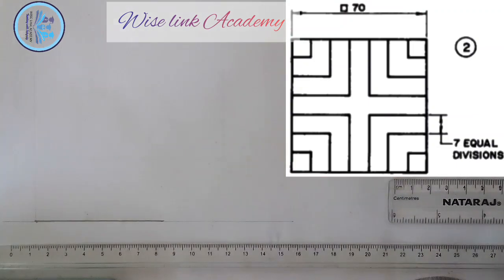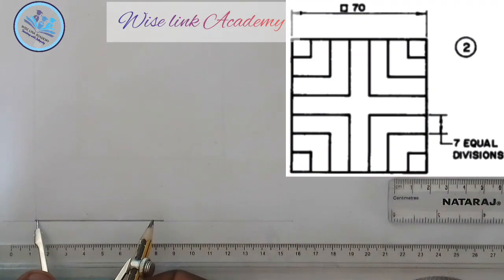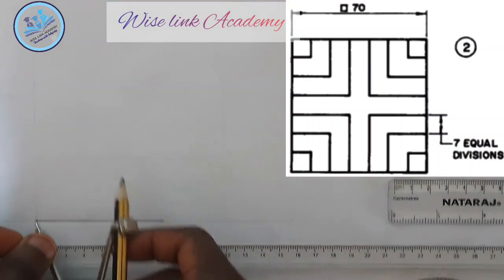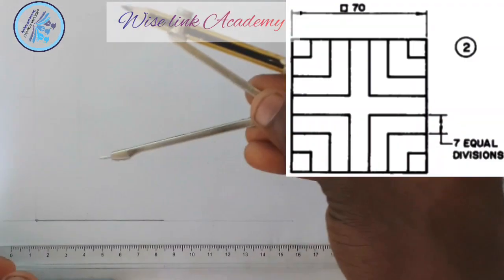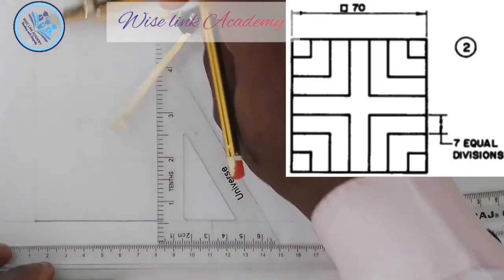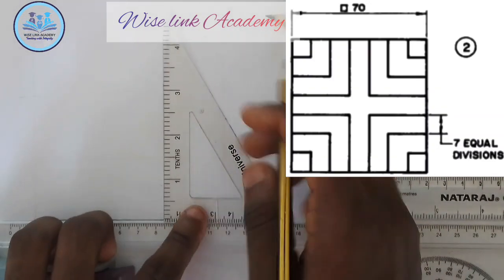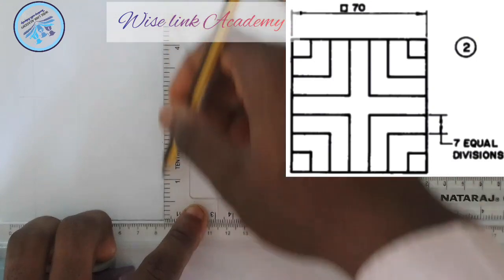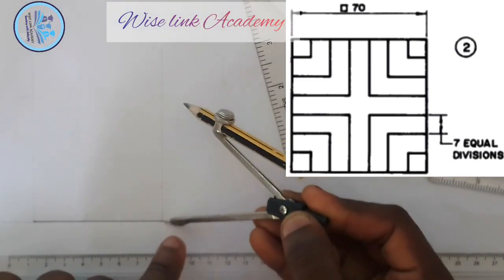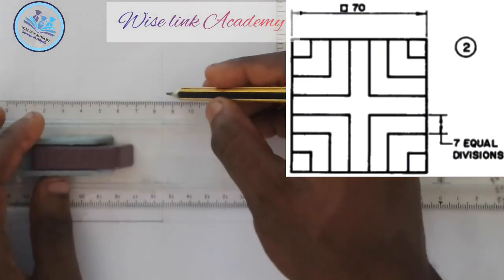Next up, what I will do now is to take my compass and measure the distance from that point here to this point. As you can see, take it this way, strike an arc up here. With that same measurement, put it down, please. Next up, you take your T square on your set square this way, take it up this way, right? At that point. Next up, take that 70 at this point, strike an arc up here. So where they meet, you close it up.